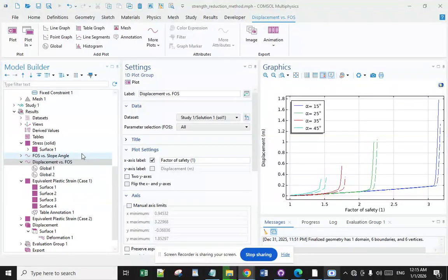This low design factor is why aerospace parts and materials are subject to very stringent quality control and strict preventative maintenance schedules to help ensure reliability. A usually applied safety factor is 1.5, but for pressurized fuselage it is 2, and for main landing gear structures it is often 1.25.